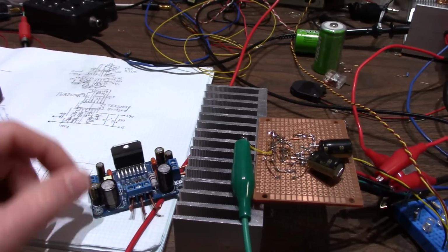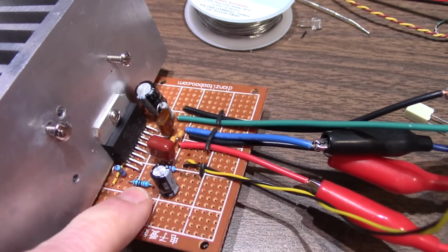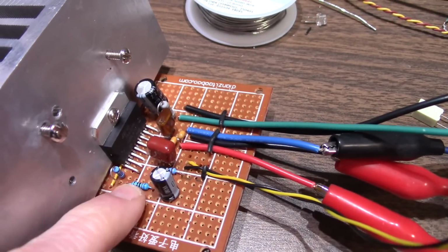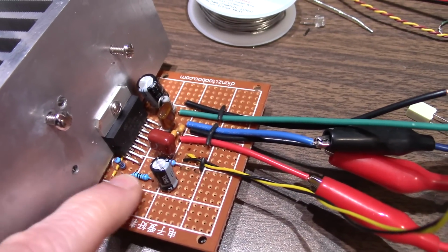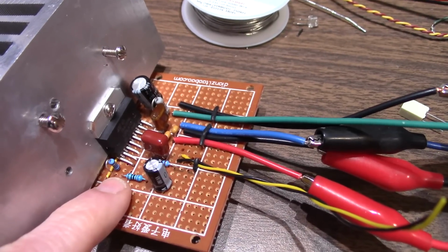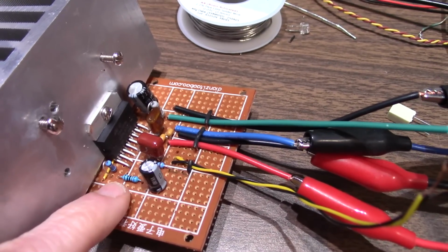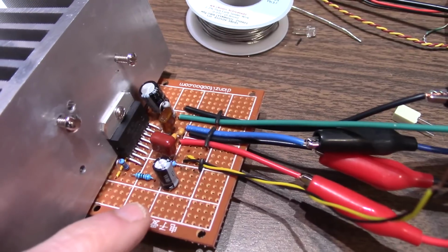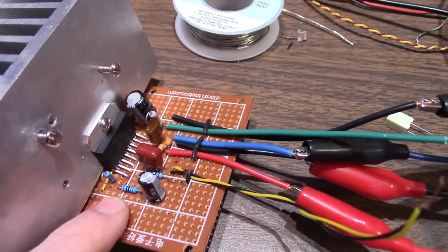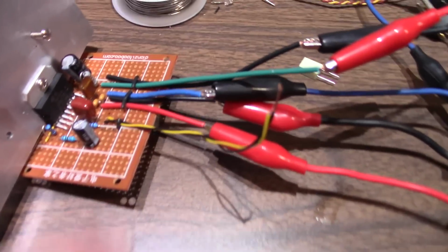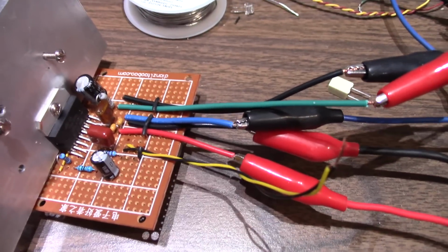Okay, I got the 680 ohm resistor installed, making sure it connected to the right position. I can't believe it. In the last video, I had the lead one position over, and the amplifier would just oscillate. I didn't see it. I was going crazy trying to figure out what the problem was. It was just a mistake. So now I have it powered up and nothing. No oscillation. Good. So we can hook it up to the Quantasylum and begin testing.